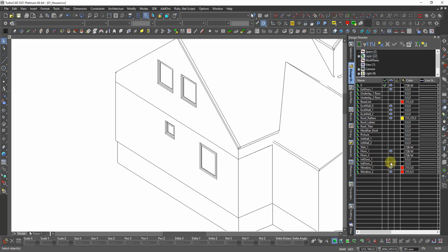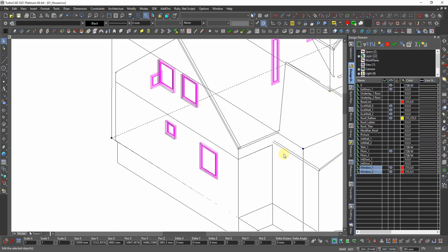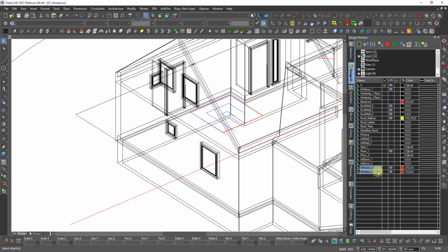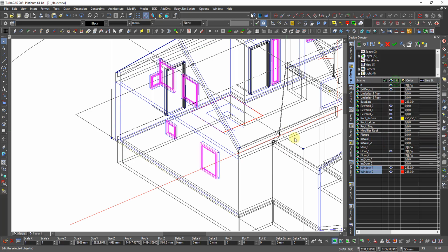Interior door we don't need to care about, but we need to care about the exterior door. But they have a different measurement. So then I select this one, this and this. Select by, escape, go to wireframe. Don't need to make it more heavy for the machine than we need to.